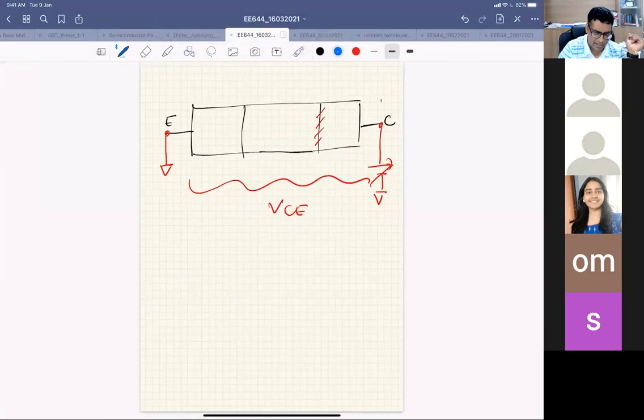Let's say there are some electrons injected. There is some positive voltage in the base, so the emitter-base junction is a little bit forward biased. So some electrons are injected here, and alpha times these electrons, the base transport factor times, will reach the collector-base junction. Since the base is open, I could have alpha equal to alpha T, because there is no base current. Whatever electrons I inject will be collected. This junction is reverse biased, so these electrons will go across the junction.